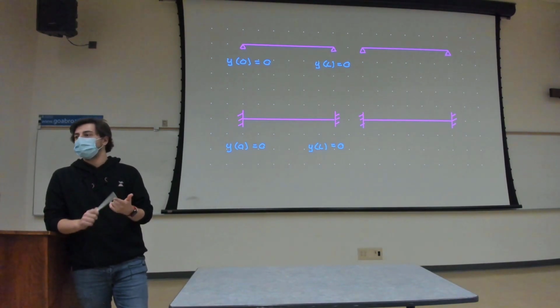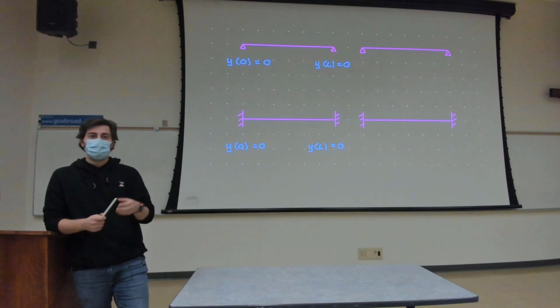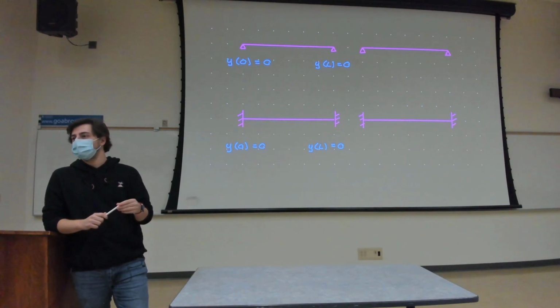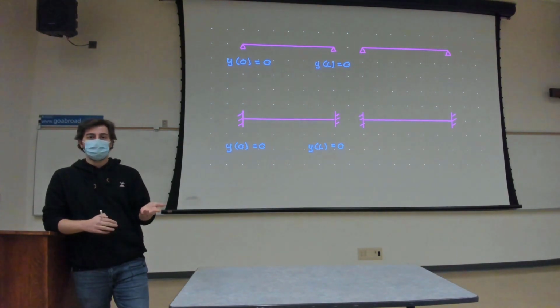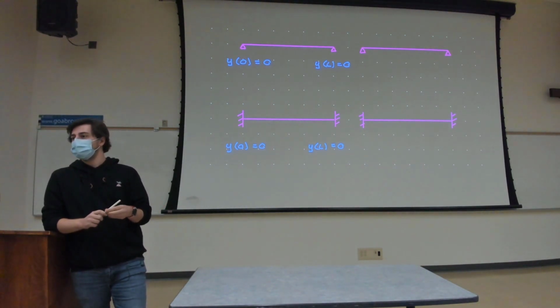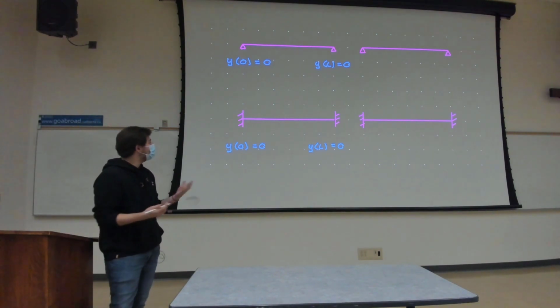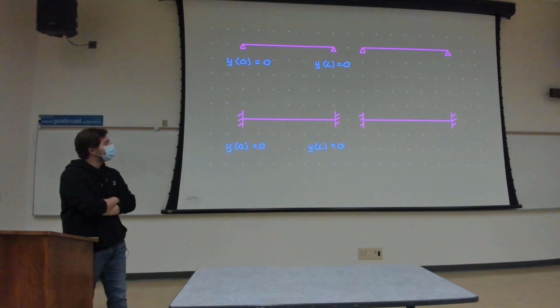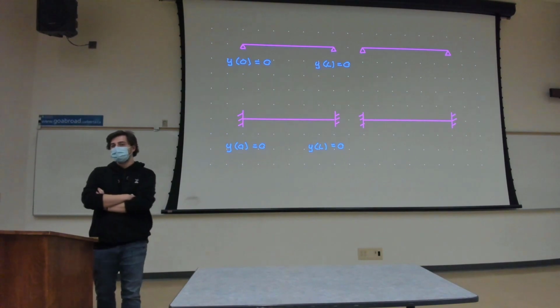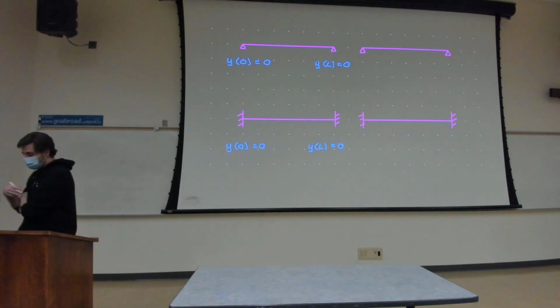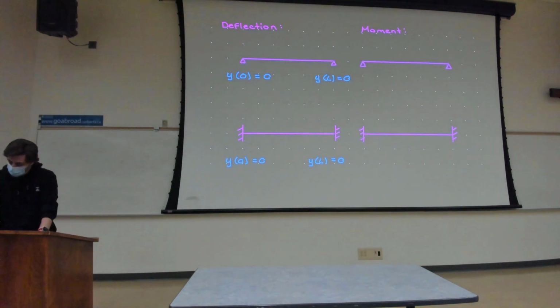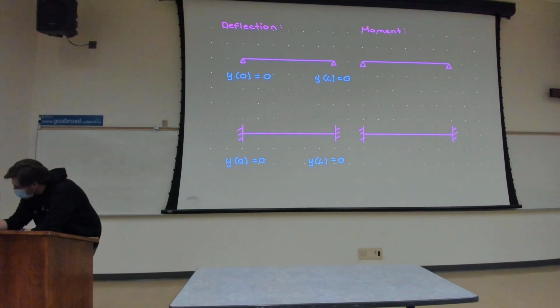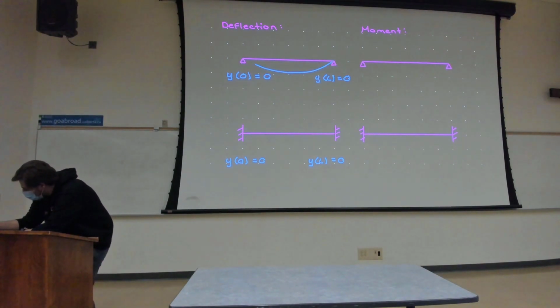Can I have a shear boundary condition? Well, let's take a step back. Is shear related to displacement? Yes. It's the third derivative. So could I have a shear boundary condition? Yes. So it's just a matter of analyzing what you have and then applying the correct boundary conditions. When it comes to the deflection of a simply supported beam, we know it's going to look something like this.